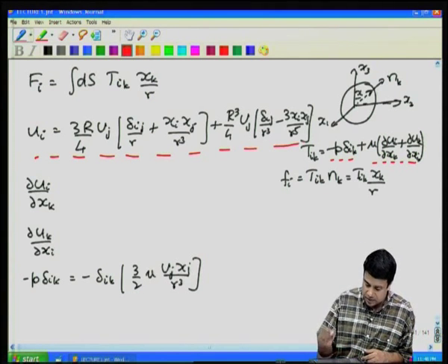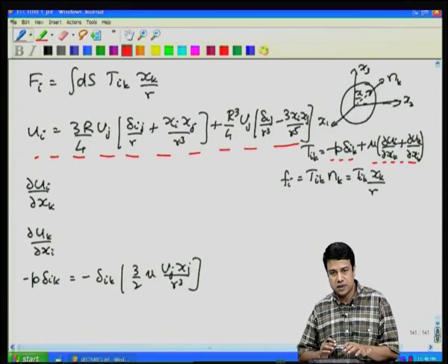We will continue this in the next lecture. Gradients of the velocity field multiplied by the unit normal, integrated over the entire surface in order to get the total force acting on the surface of the sphere. The prediction of this total force, as you probably know, is given by Stokes law. We will be able to derive the Stokes Law solution by this method without reference to the individual components of the force, but rather just taking the vector velocity, the stress, integrating that to get the total force.